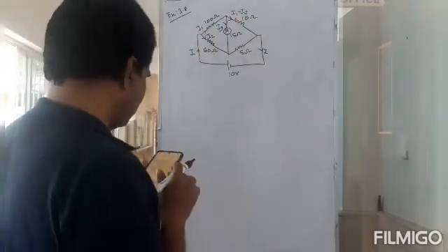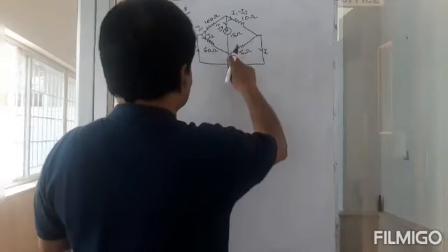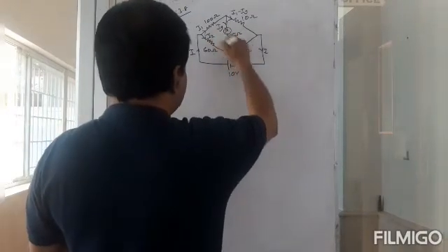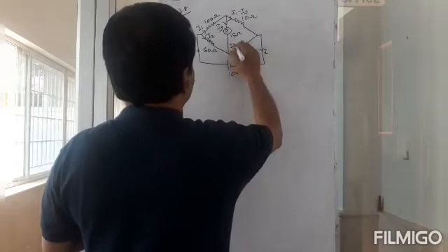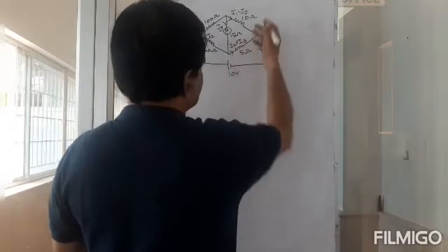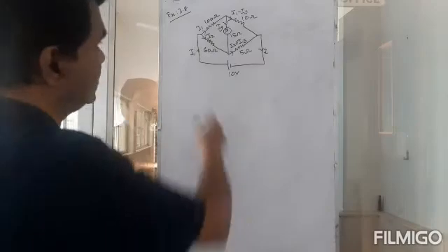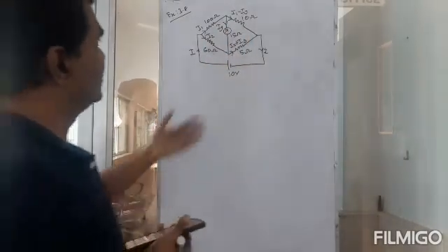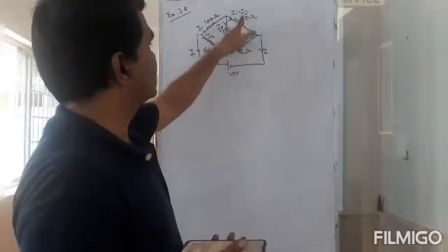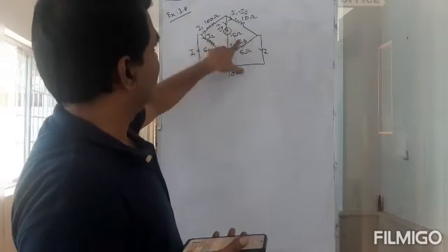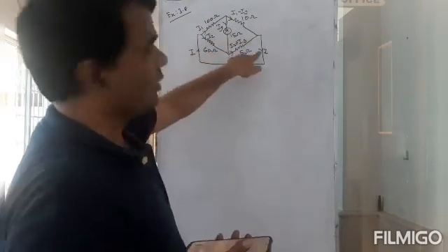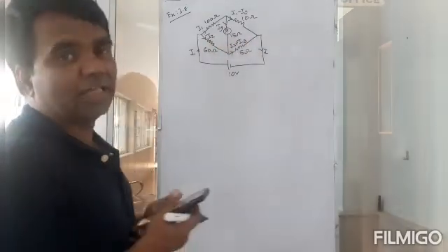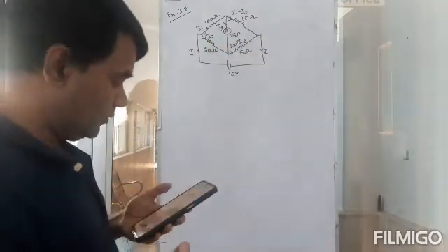Likewise, what do you have here? IG is coming here, I2 is coming here, so this must be I2 plus IG, which is equal to I4. You can add these: I2 plus IG and I1 minus IG. When you add these two, IG and IG cancel, and you have I1 plus I2, which is equal to I. So all tallies properly.